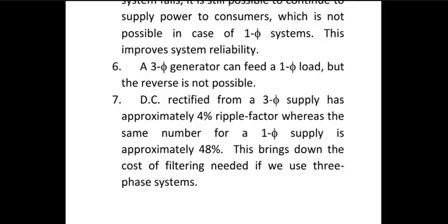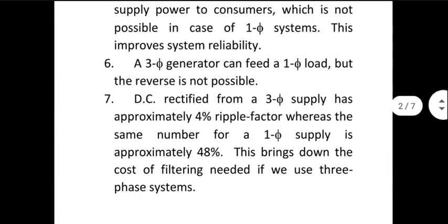That means the filtering, the capacitor value required, and etc., even Zener diode requirements may be much less severe if you are designing a power supply to convert three-phase AC into DC compared to single-phase AC into DC. There's a lot of work here that may be required to prove all this, but let me tell you the final result. This is for sure. The filtering requirements in case of a three-phase AC to DC rectifier are much less severe compared to the same in a single-phase rectifier.